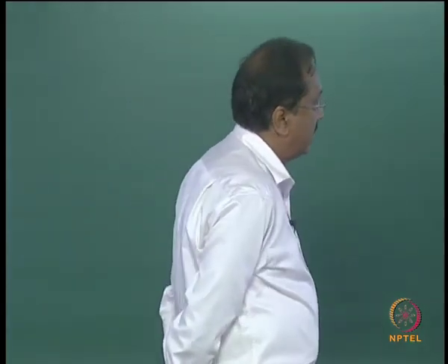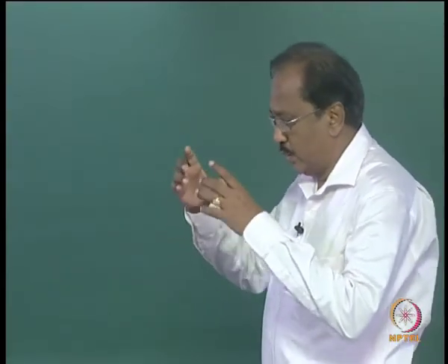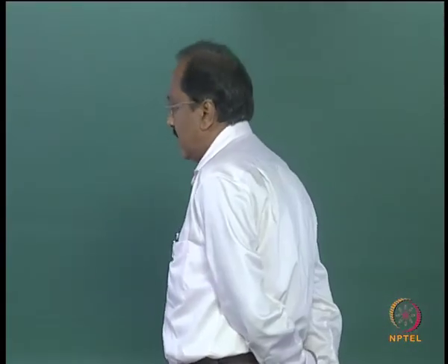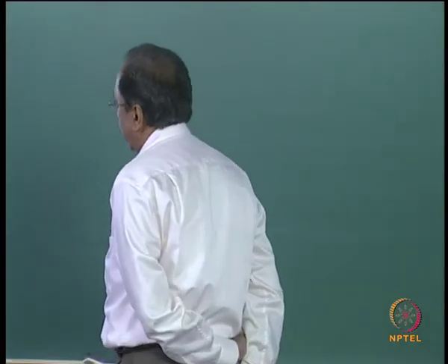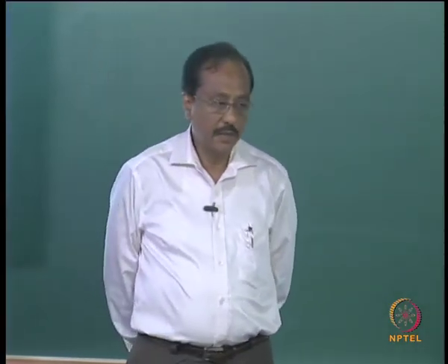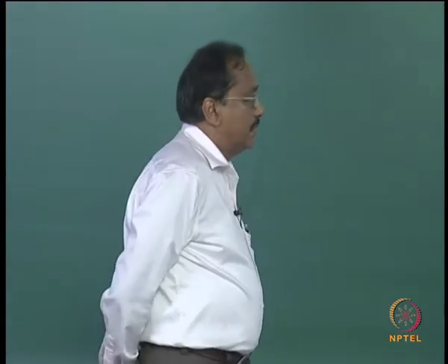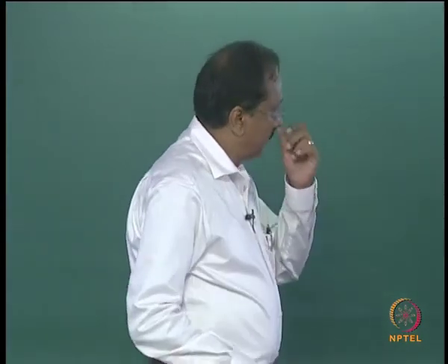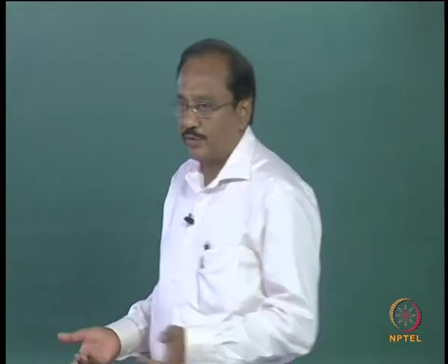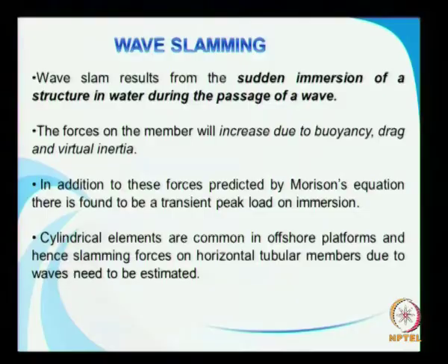Wave slamming occurs due to the sudden immersion of a structure in water when a wave is propagating in that location. So you expect an impact force, and it is an impact force. The forces on the member will increase due to buoyancy, drag, as well as virtual inertia.